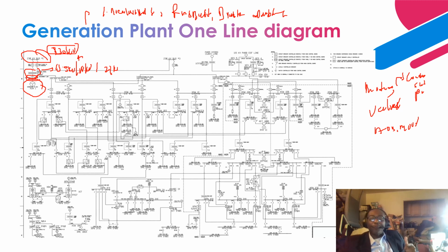So if it forms the water condensate, you need a pump motor scheme to pump the water to the next level as part of the cycle, right? Because you're pumping the water towards the boiler, right? Okay, so once the condensate pump motor pumps the water, then it goes to the boiler feed pump.